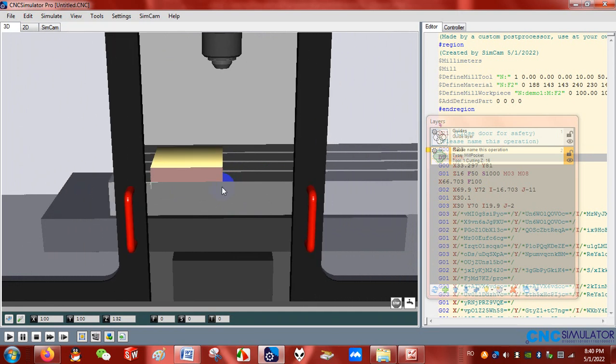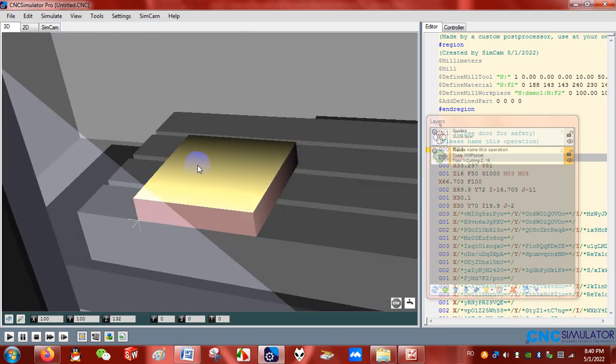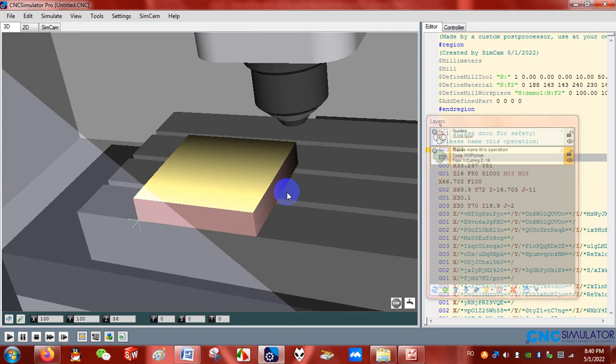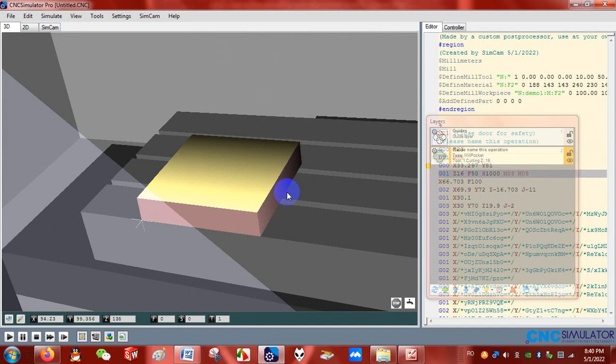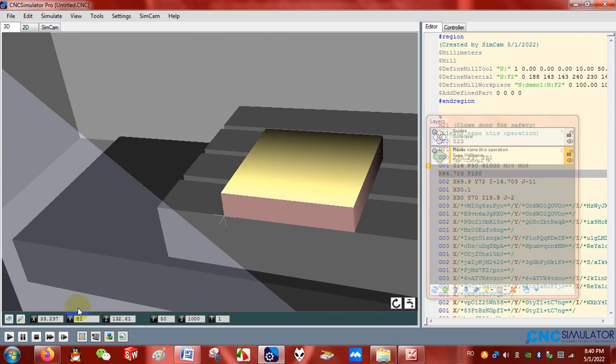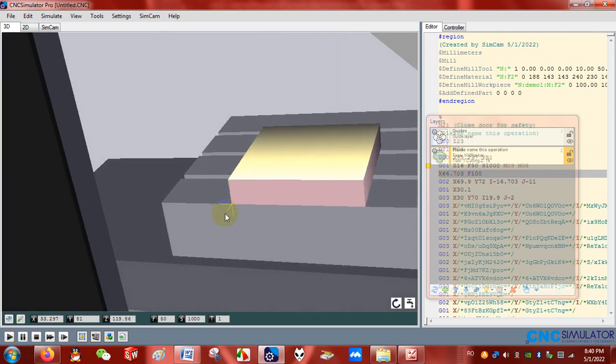So the M21 command will close the doors of the machine. We will have now the cutting tool. We can observe here the zero of the reference point, which is put at 0, 0, 0, no?